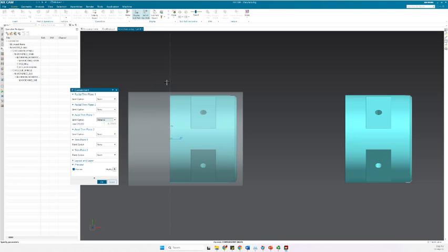If I put 0, it means that the tool will not move after this one, which could be fine, but then again, I can put a little bit more material so that I don't have any problem of extra material left here. So I can put, for example, -5. And that's about it.